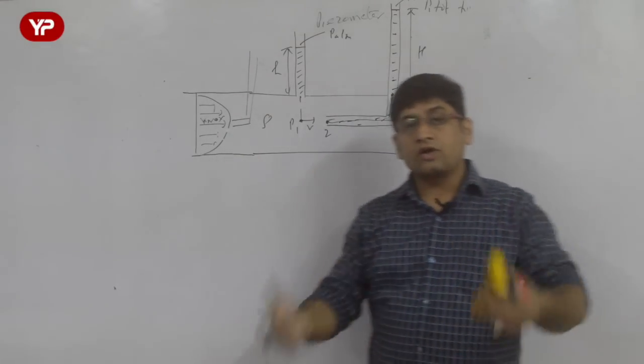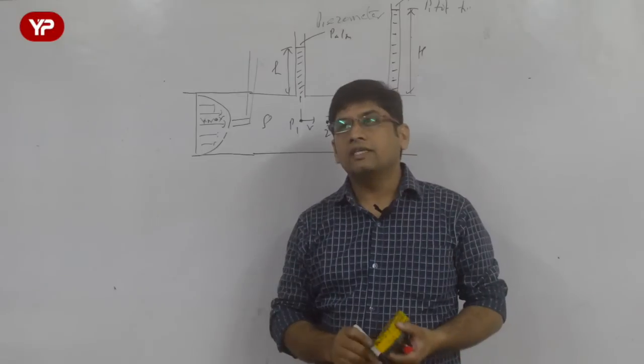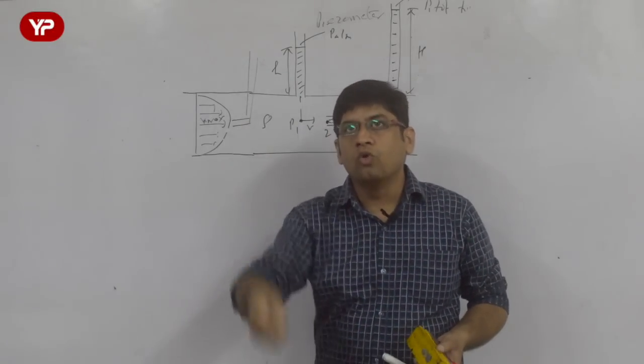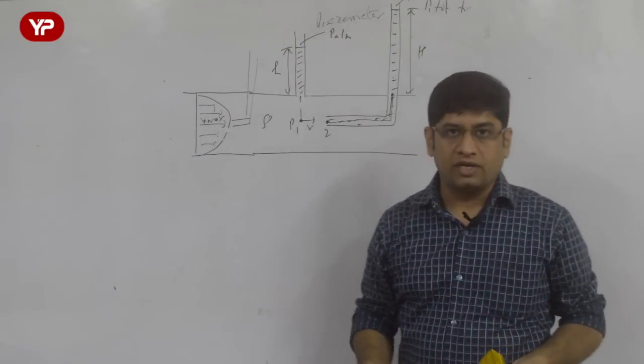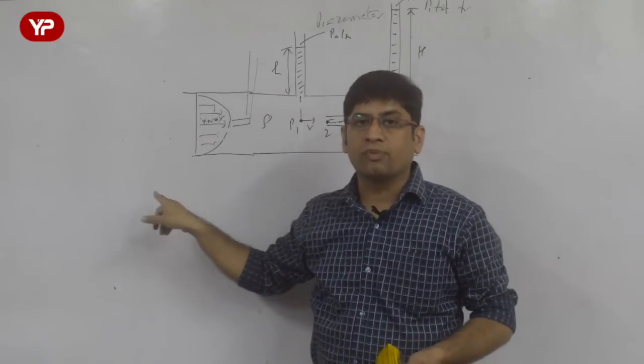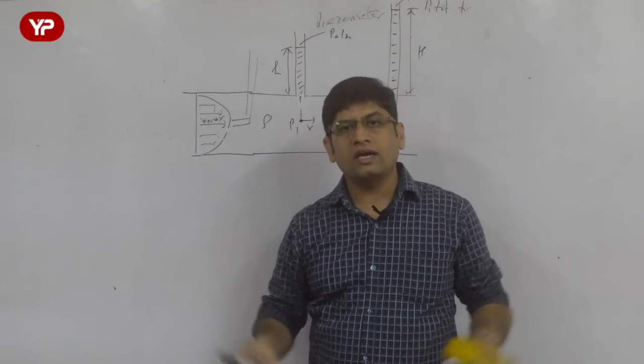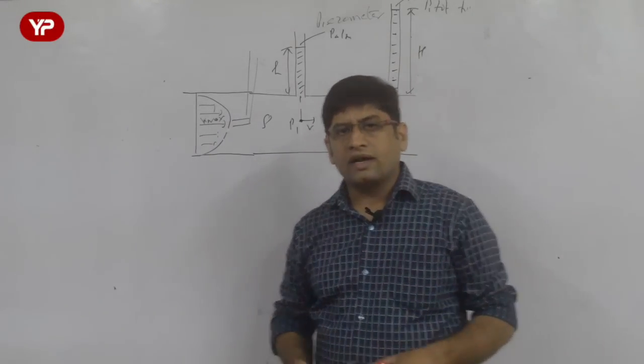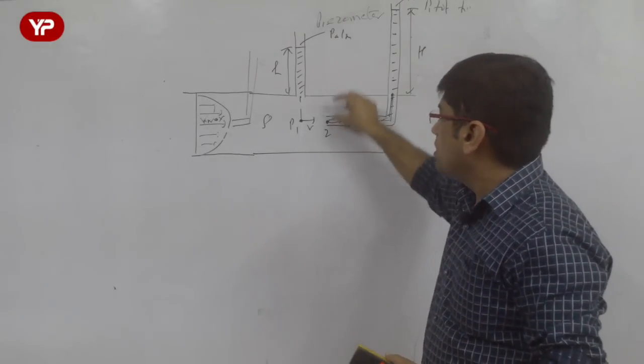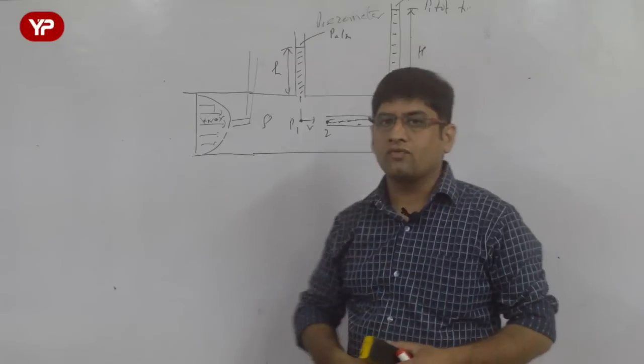So if I want to find out the velocity profile, it is important for me to move the pitot tube and get velocities at different points, and that way I can make the velocity profile in the pipe flow or any other particular flow. Even in river flow, I get a profile like this. So if I move the pitot tube top and bottom, velocity of flow will decrease.